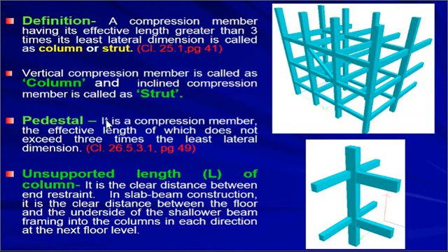Pedestal is one more term which is normally used. It is the compression member, the effective length of which does not exceed 3 times the least lateral dimension. Well, pedestals are small columns having less length. Some terms are important here.